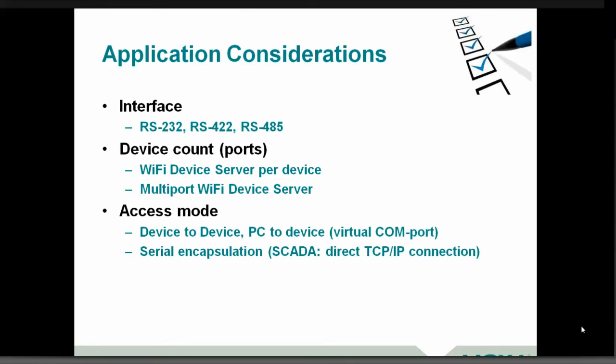If you're doing SCADA and you have a favorite SCADA software, and I can go off about half a dozen different types of packages for that, most all of those packages utilizing your existing industrial drivers have some means of doing serial encapsulation, which is a checkbox on your setup for that, to enable redirecting that serial communications over a TCP/IP connection. So think about the access mode to make sure that your serial device server supports that.